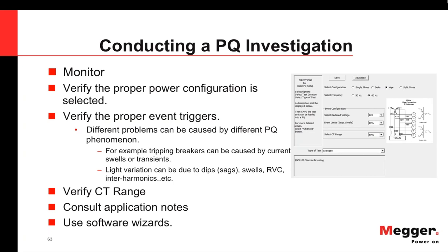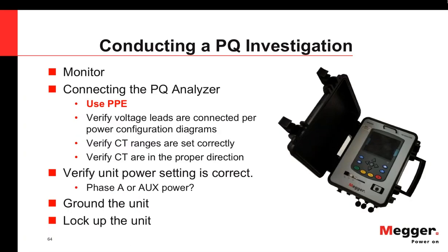Okay. Now, we have the monitor set up. We're ready to go. Now we have to make sure that it is programmed properly. We want to make sure we have it set up for the proper power configuration and the proper event triggers are set. Different problems can be caused by different PQ phenomena, so we want to make sure we're looking at the right things. We also want to verify our CT range.